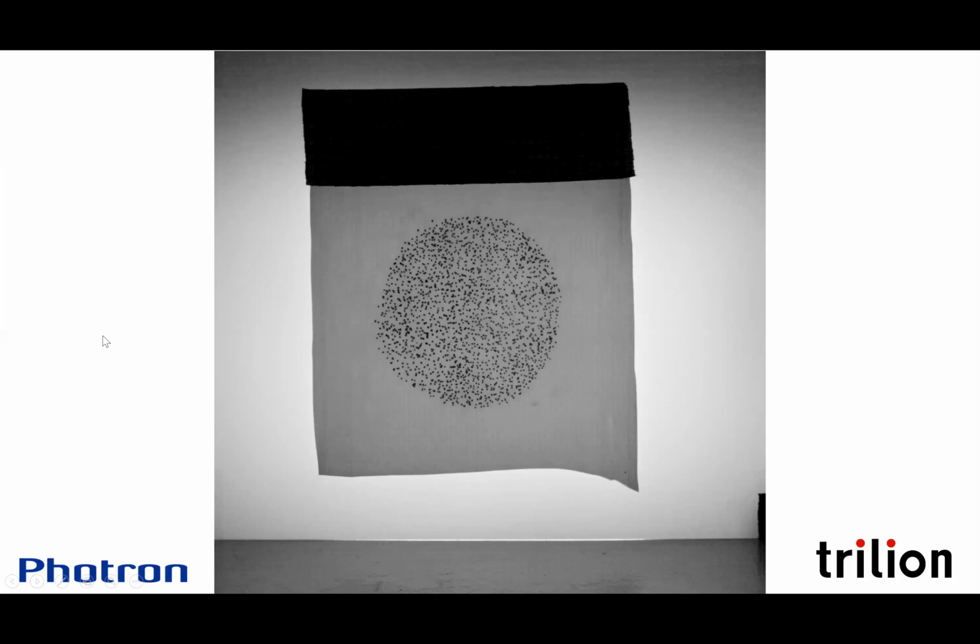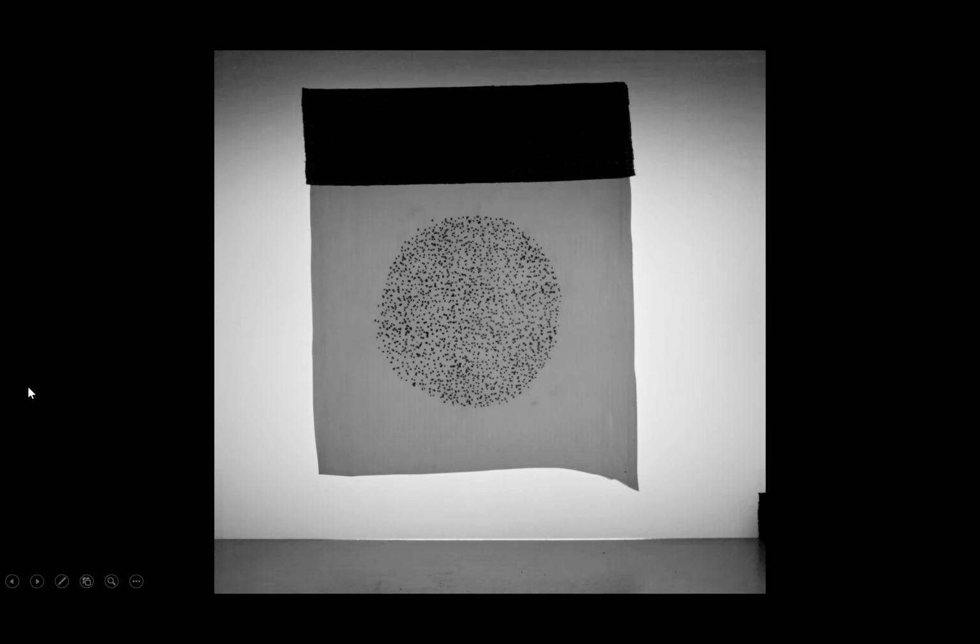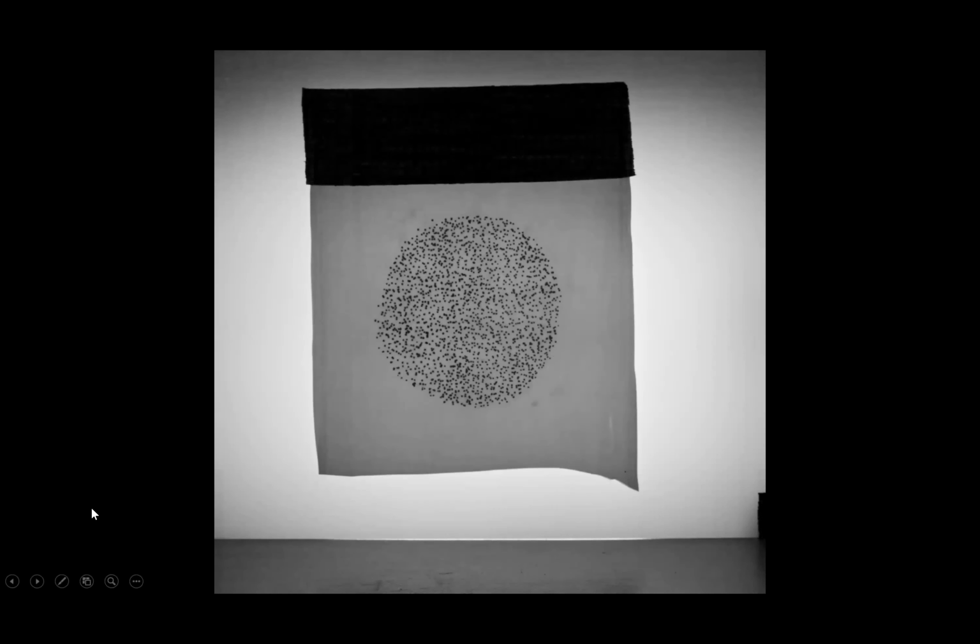All right, so now this is the exact same video that we've just turned on the HDR. You're still going to see the saturation on the outside of the image. Again, we don't care about that. But actually in the area of interest now, we have very little fluctuation in the grayscale. So when the image was darker, we're just pulling up some data out of those lower bits that you weren't seeing before. And when the backlight brightens up, we're just using those upper bits that you were seeing before. So now we've got a very stable area of interest. And just a quick side by side here, just to see the difference.